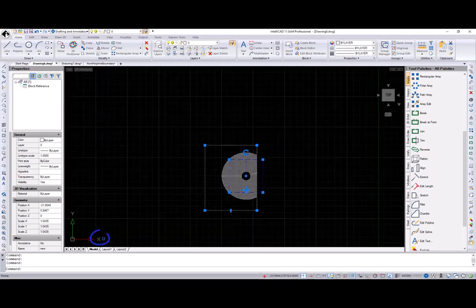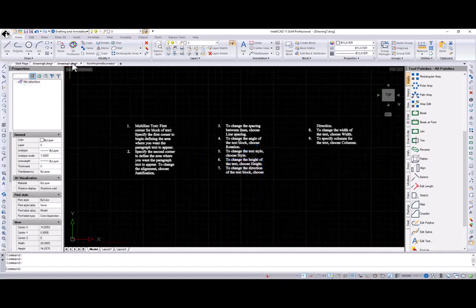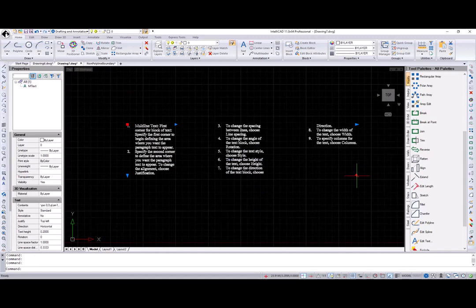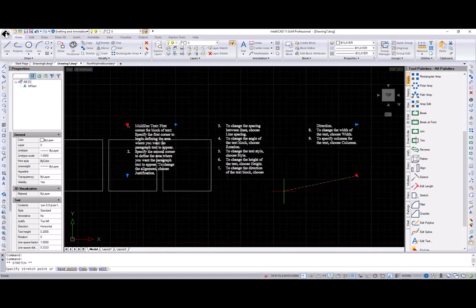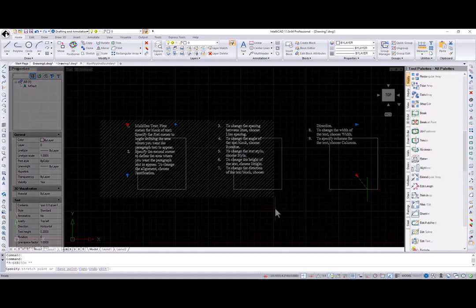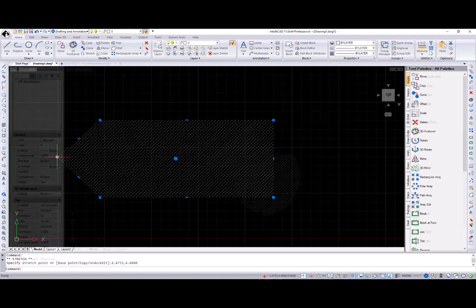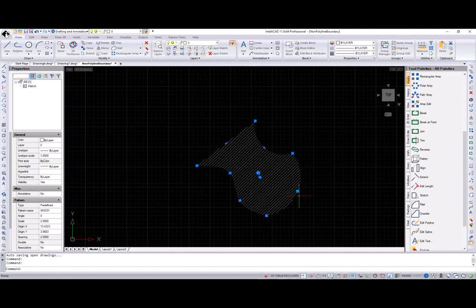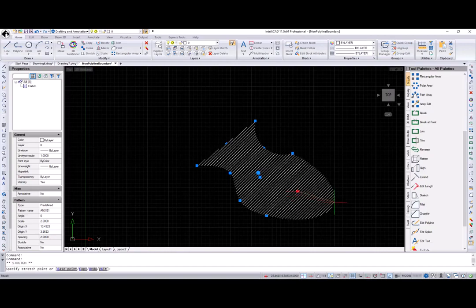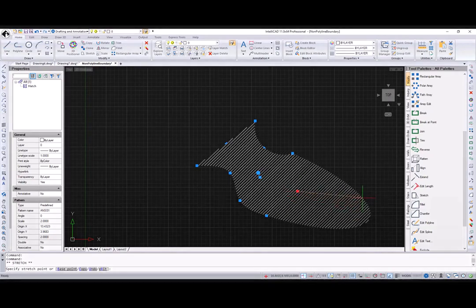Insertion point grip looks different now. Enhancements were made to improve multiple grip editing. Here is an example with multi-line text. Ability to add vertex to the hatch boundary. An elliptical segment of associated hatch can be edited using ellipse grips.